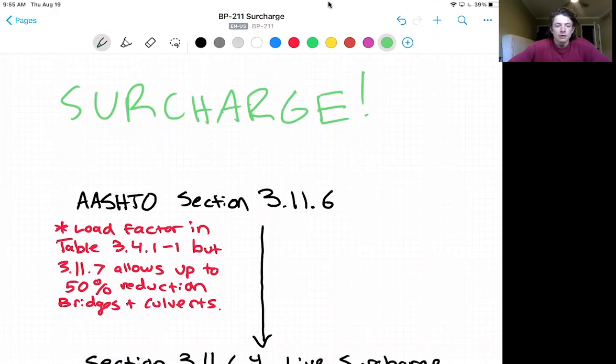Now that we've established the what, we need to define the actual loading magnitude from the code. But as you may know, this can be extremely different. The lateral surcharge load magnitude is going to be a function of the distance from the surface loading and the size of the surface loading.